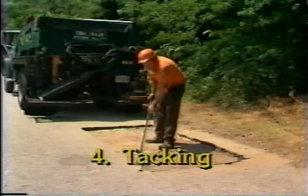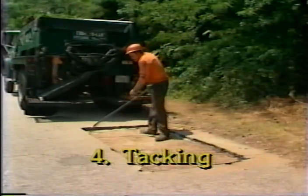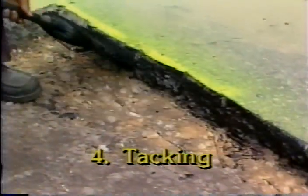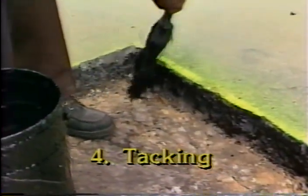4. Tack the sides and bottom of the patch area. Preferably, spray the tack with a wand. Brushing is acceptable if a spray applicator is not available. A thin, uniform coating is desired.